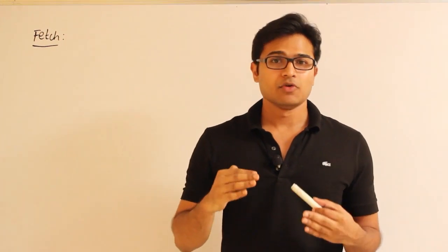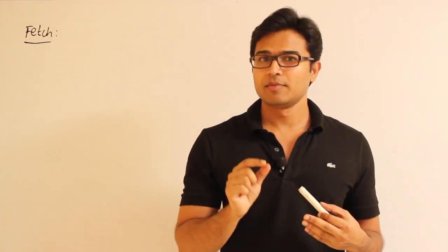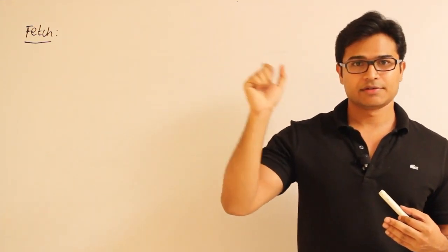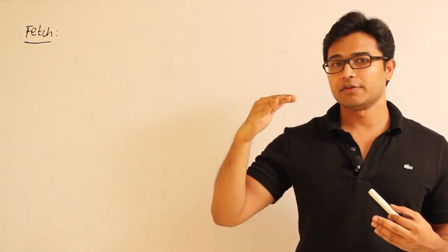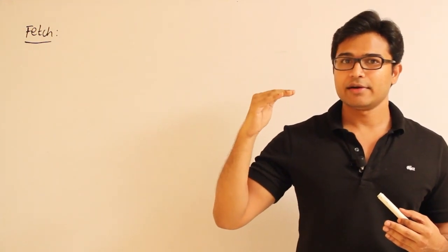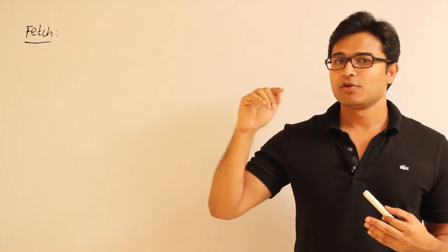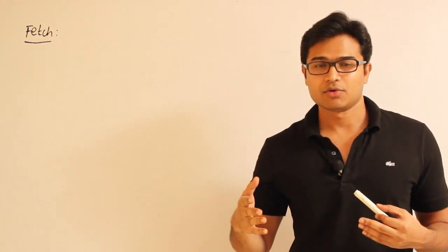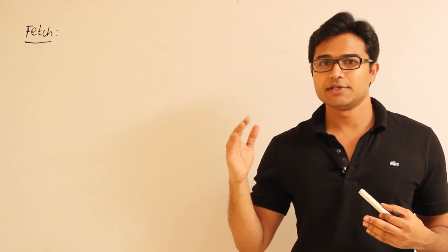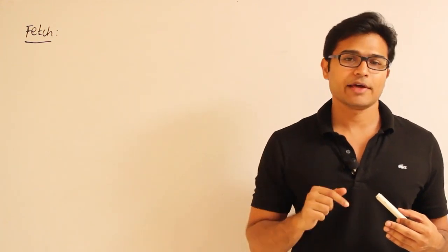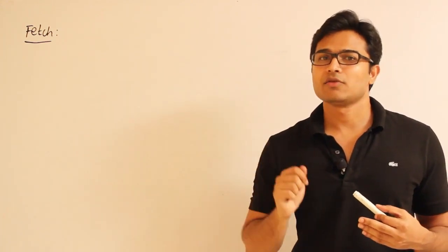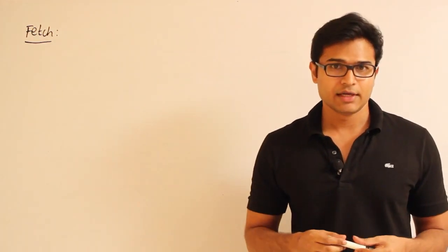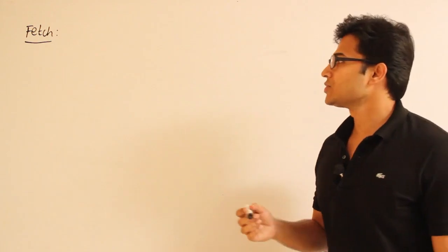So assume that before we start anything, the program counter is loaded with the starting instruction address. If the program is starting at address 100, then the program counter should contain address 100. Before you start any program, generally you clear the sequence counter. Then automatically T0 will be generated, or T0 will get highlighted. Got it? So when we start, we are going to start with T0.